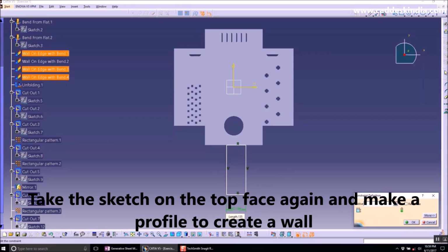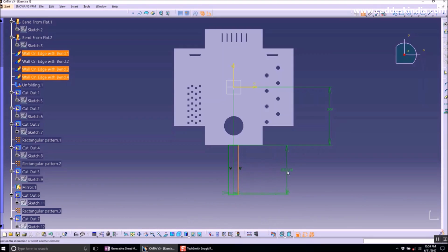Let's give it a horizontal constraint of 50, and the distance from the vertical axis to be, let's say, 25. The other thing is to define the top edge, the position from the horizontal axis, at 300, and finally the height of this rectangle to be, let's say, 125.